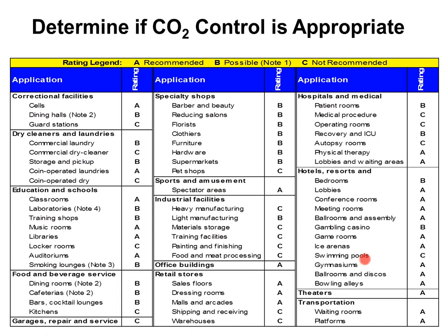The B's are the maybes, right? So training shops, laboratories, well, what are you doing? The dining room at a restaurant, well, the dining room we can do DCV on, absolutely. The problem is a lot of engineers, or non-engineers for that matter, design the dining room ventilation air to also be a portion of the makeup air unit for the exhaust fan. In my world, the kitchen should be isolated, and the exhaust fan should have its own dedicated makeup air unit sized for the exhaust fan.